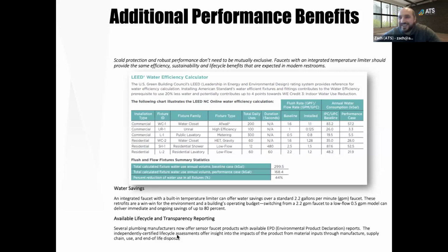Well, I was going to chime in when it comes to water systems. One of the other issues with point of use and some of the other mixing valves: say you want to do a larger bank of labs, you may put a single mixing valve for say 5 or 6 labs. But if that minimum activation level for that mixing valve is too high, say it's above 0.35, then you can't be using it. That's one of the challenges that mixing valves have had.